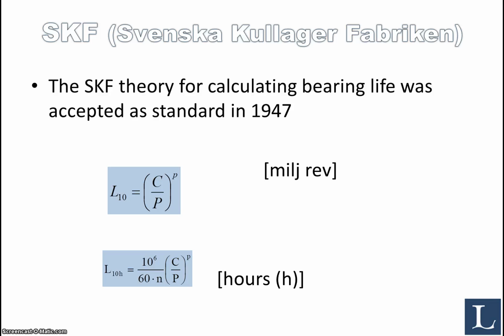Now, when we talk about the life of the bearing, SKF have a theory for calculating the bearing life. This has been around for many years, accepted in 1947, called L10. And basically what you do is you compare the load rating of the bearing to the load that is applied to the bearing, and this right here is chosen whether it's a ball bearing or a roller bearing.